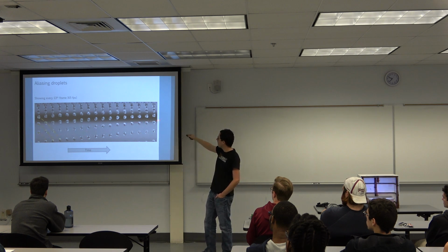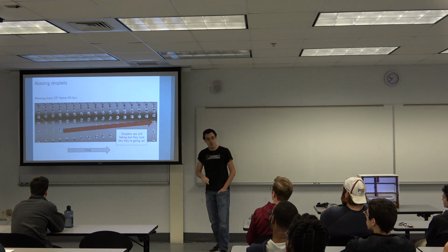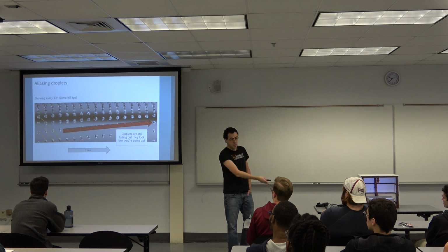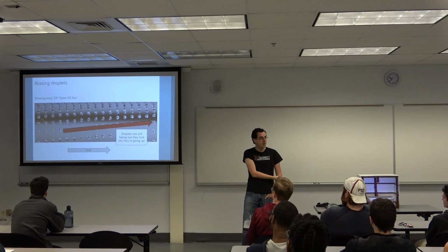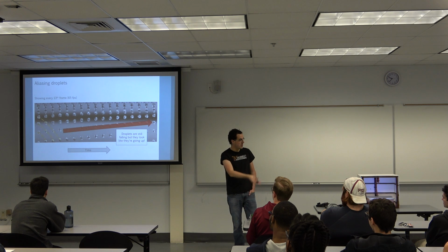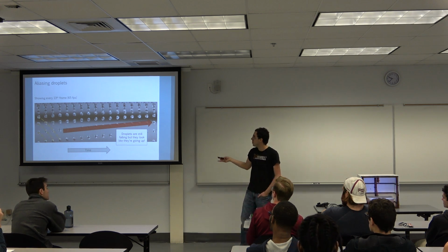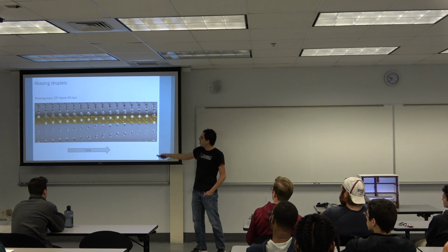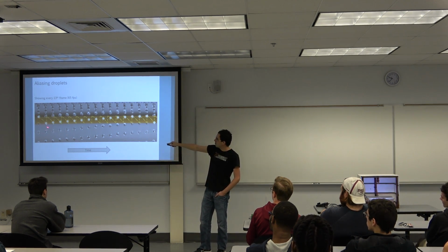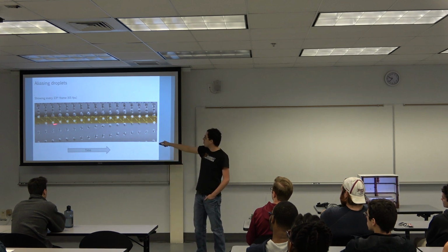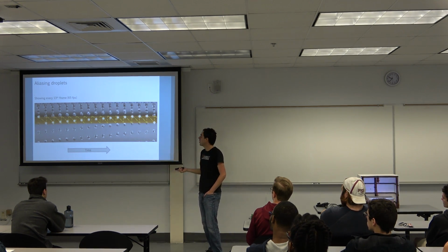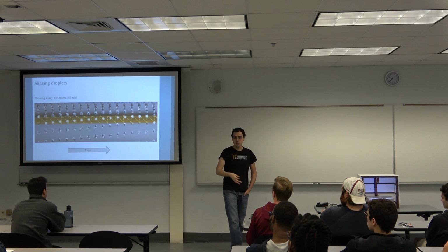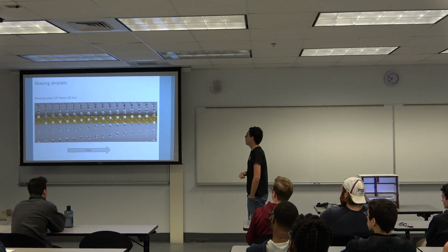And if you see here, now it looks like the droplets are going up. This is the effect that you're seeing when I'm flashing the LED at a frequency that is very close to the frequency of the formation of the droplets. If now we show the waveform, we can see that the waveform now looks at the wrong frequency, and also the droplet direction looks wrong. So we got both the frequency and the direction of the movement wrong.